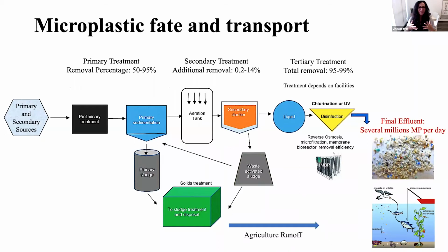So think about if you have water with sugar, how you get rid of the sugar. What we are doing in this wastewater treatment plant is that anything dissolved is transformed into bacteria, into a solid mass that we can then separate using a sedimentation tank. We are just changing the phase of the contaminants from dissolved, very small particles to bacteria, and usually bacteria get together and form floc. That floc can then be easily removed from the wastewater treatment plant.